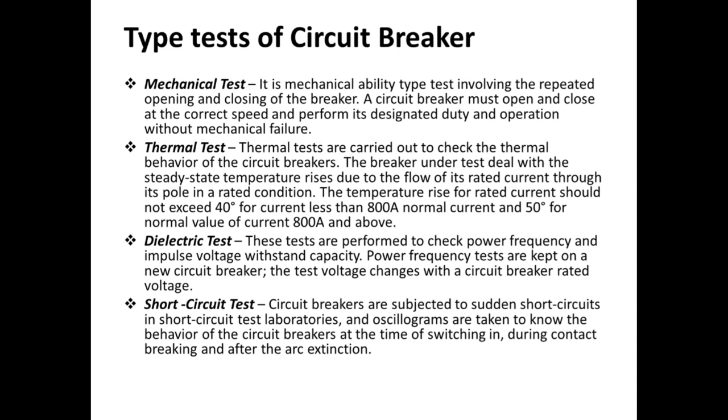Short circuit test. This is a popular test among all these tests. Circuit breakers are subjected to sudden short circuits. In short circuit test laboratories, oscillograms are taken to know the behavior of the circuit breakers at the time of switching, during contact breaking, and after the arc extinction.